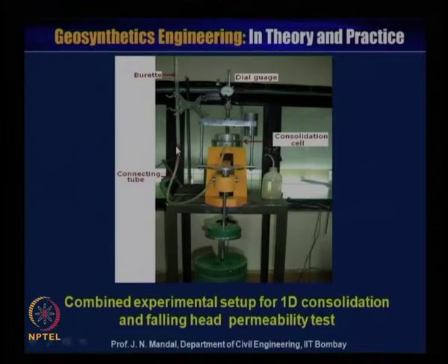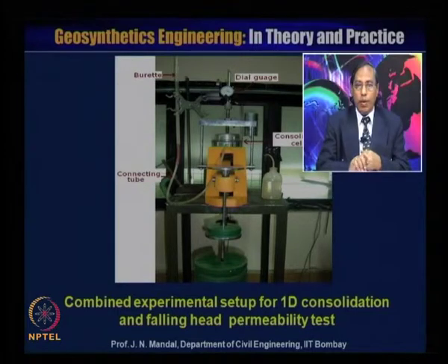So, this is the combined experiment setup for one dimensional consolidation and falling head permeability test. You can also indirectly determine the coefficient of permeability from the consolidation test.